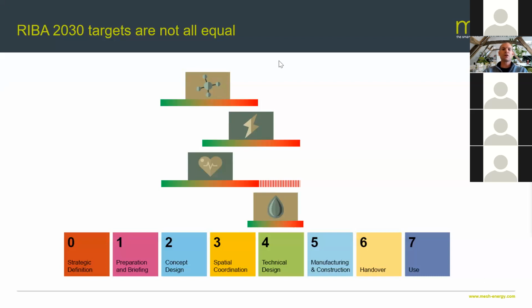So again, this is just to highlight some of the issues here. And one final thing to bear in mind, and you probably think about this when I mention it, is health and well-being. You can conquer health and well-being by very passive means: passive ventilation, sensible building design, looking at your glazing carefully, using geometry of the building, overhangs and so on to minimize overheating, to minimize the requirement for cooling, and really have a fantastic environment in the building through good design.